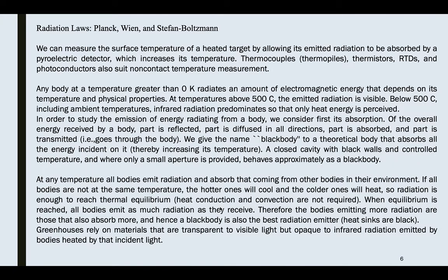Radiation laws: Planck, Wien, and Stefan-Boltzmann. We can measure the surface temperature of a heated target by allowing its emitted radiation to be absorbed by a pyroelectric detector, which increases its temperature. Thermocouples, thermopiles, thermistors, RTDs, and photoconductors also suit non-contact temperature measurement.